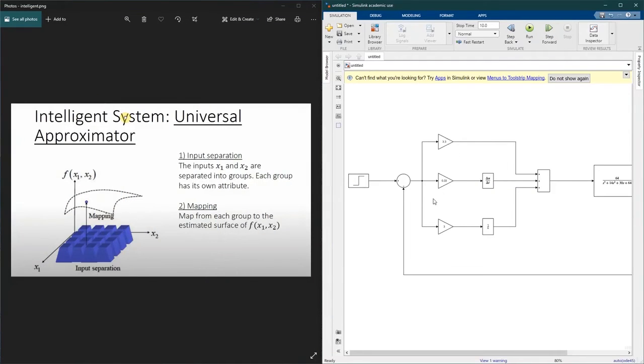Here, these 3 constants, but if the transfer function has changed, like I said in the first clip, PID cannot control the response. Error may be 0, but the response will change, and that cannot be accepted in some systems. If we care about response, fuzzy logic will fix this problem. But for accuracy, maybe it is not better than PID. Steady state error may be more than PID because PID has an integrator.